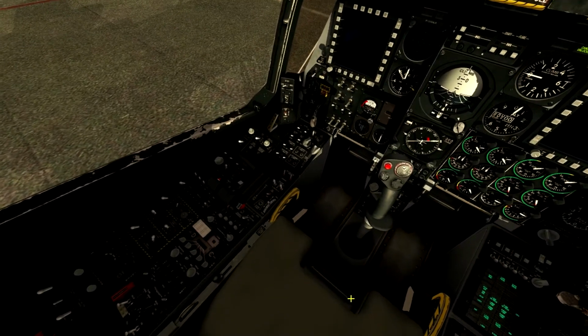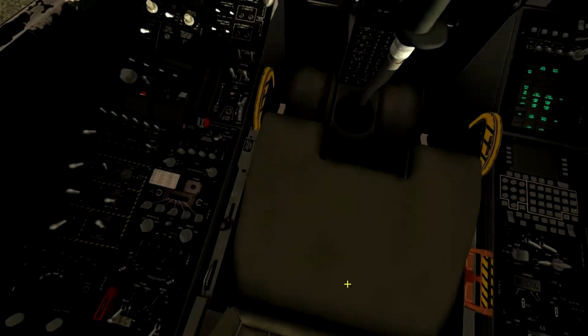To do the UHF radio, it's a little different. First of all, we have to right click this to set it onto main both, and the radio will turn on. And you see we have a bunch of twisty selection dials which go to a number. So if we want to go to 259, we've got 25 already, and this is 1, so we want to change that. So we edit this dial until we get 9, and then we've got 259 programmed in.